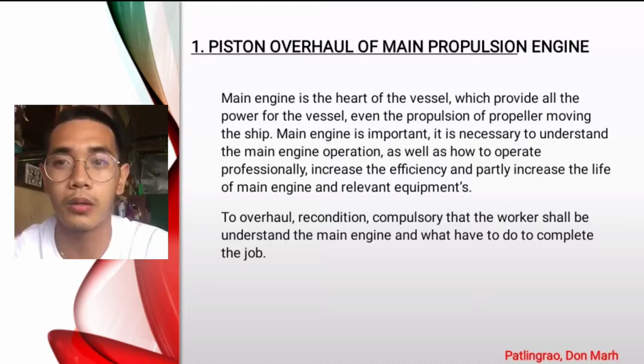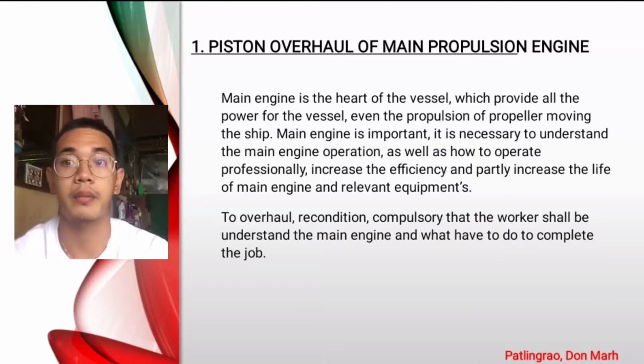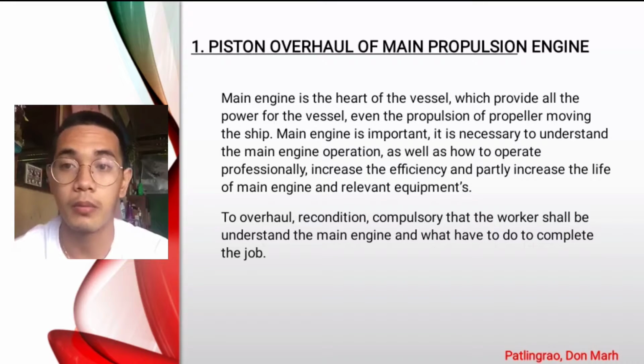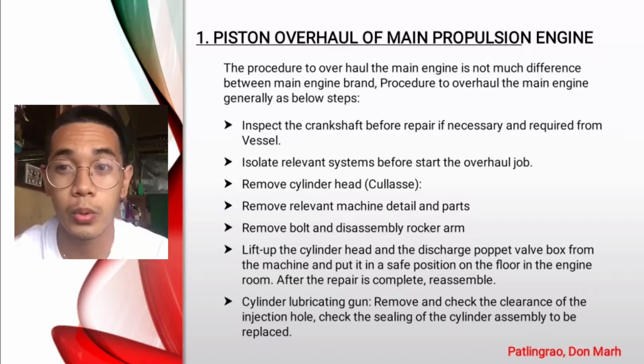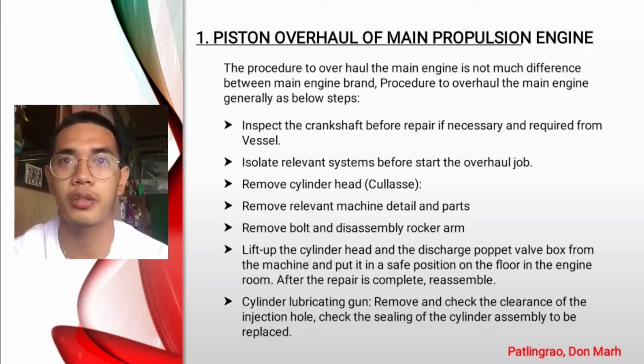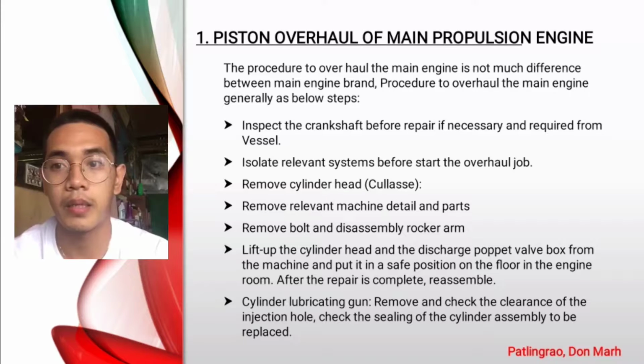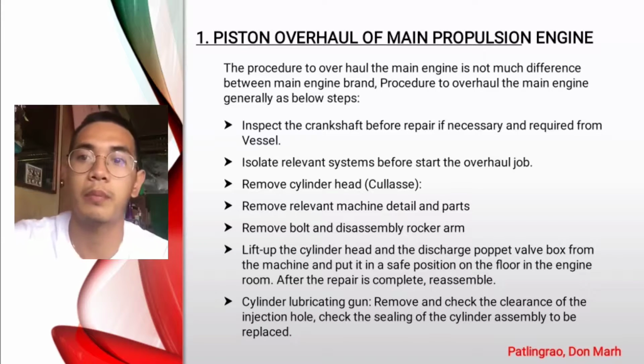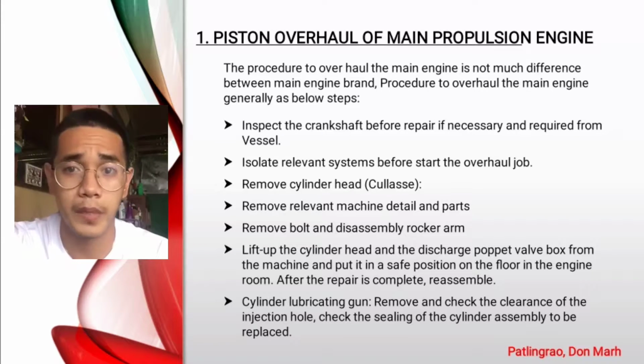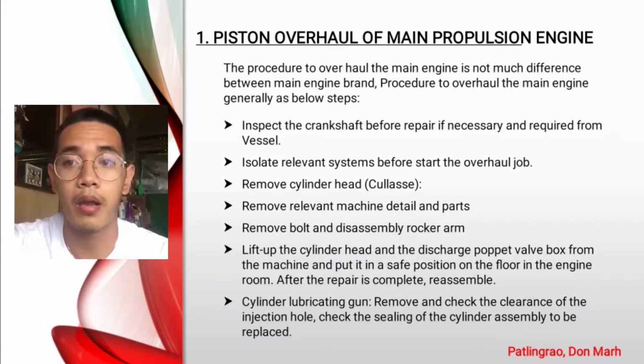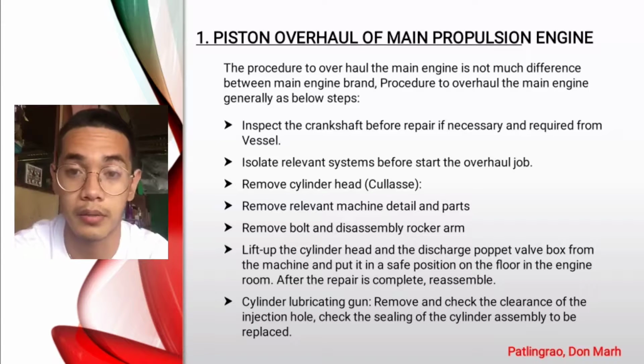To overhaul and recondition, it is compulsory that the worker understands the main engine and what has to be done to complete the job. The procedure to overhaul the main engine is not much different between main engine brands, so the most famous and popular main engines can be listed. The first procedure is to inspect the crankshaft before repair, if necessary, and from the specific vessel.